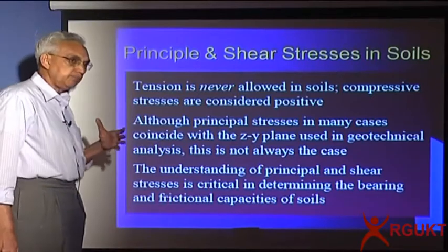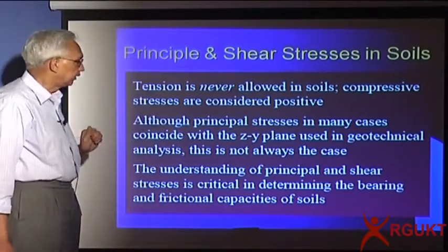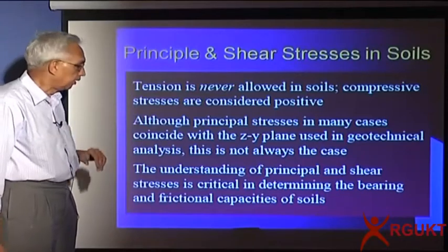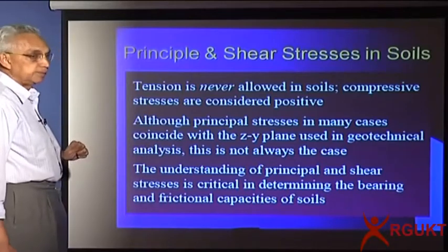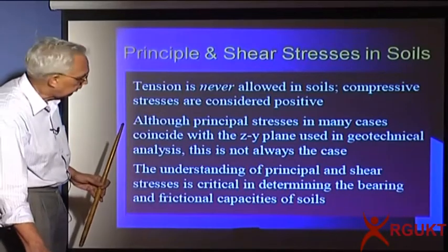We assume as if the vertical stress is the major principal stress and the horizontal plane is the minor principal stress, but in some loading situations they may not be the same. So you have to be careful about assuming that.